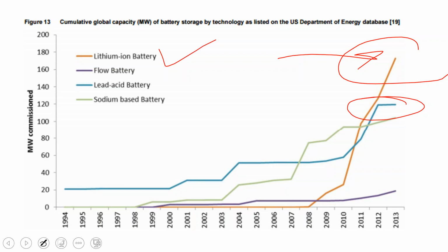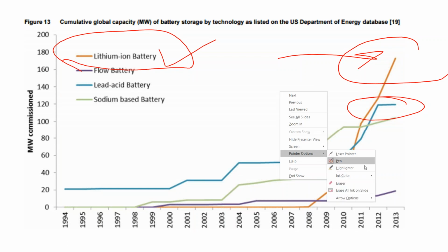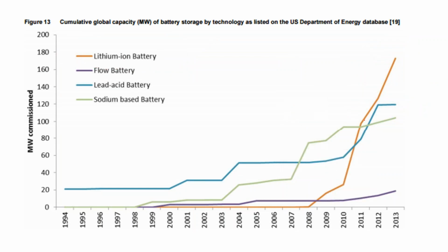And then, to some extent, there's the impact of the tax credit, where if you get 30% off everything in the store, you might be more likely to go and upgrade a battery to a better technology. But really, where I see battery selection coming into play is the question of, do you need a battery that is for almost 24/7 operation, like in an off-grid home, for a large usage, at which point you might be in lead acid just because of cost.